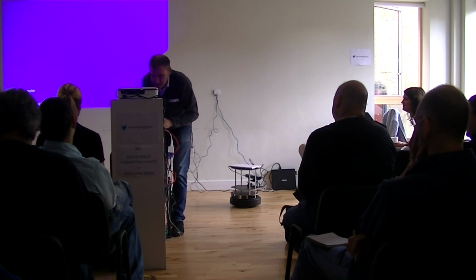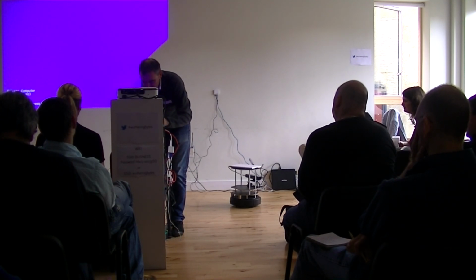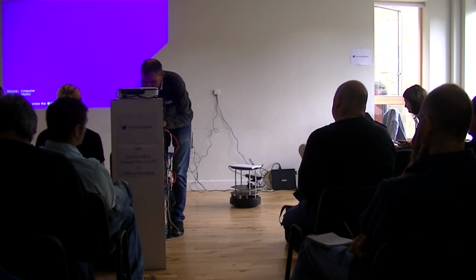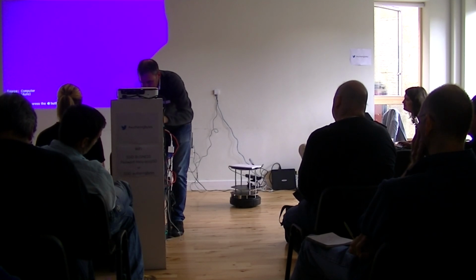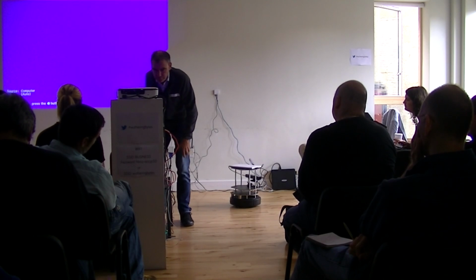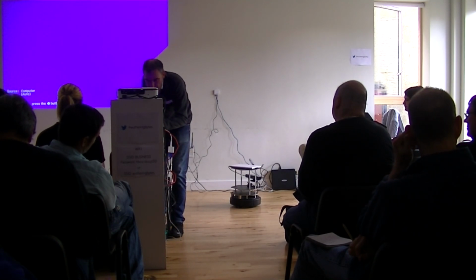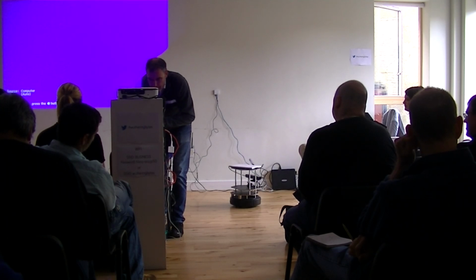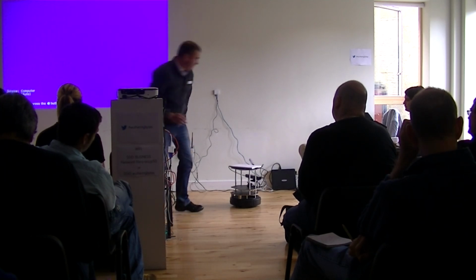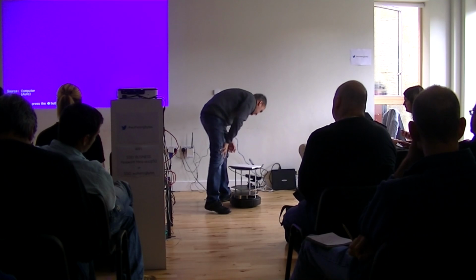Yes, I've got the address I expect. Right, okay. So the first thing I'm going to do is SSH into the TurtleBot at 192.168.0.101. Okay, while I was thinking about that, I'll remember to turn the base on, otherwise it's not going to move.